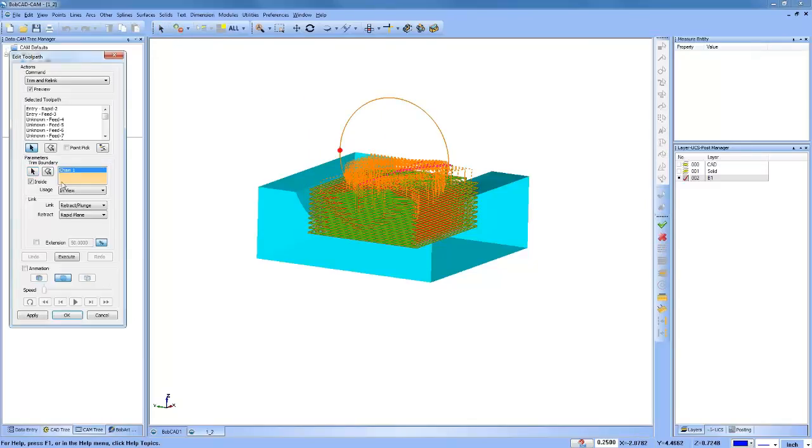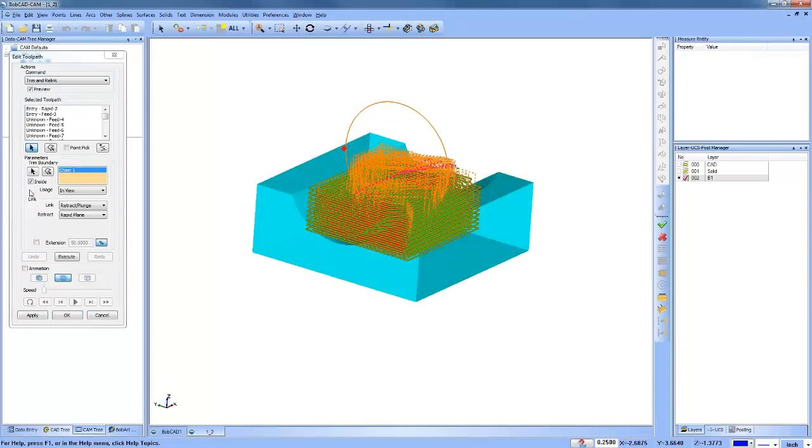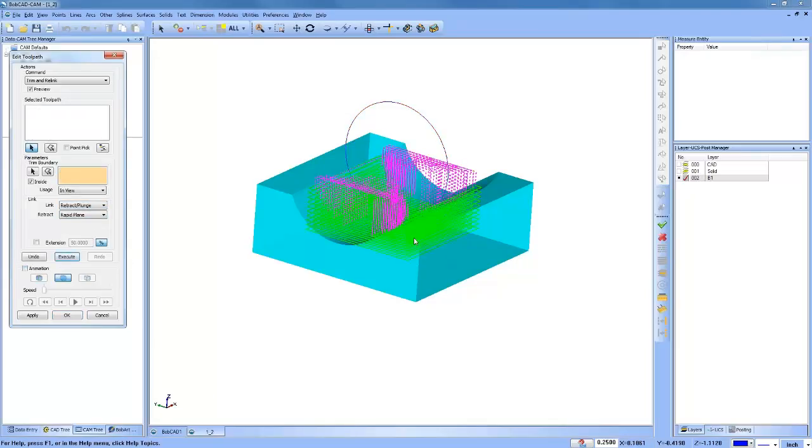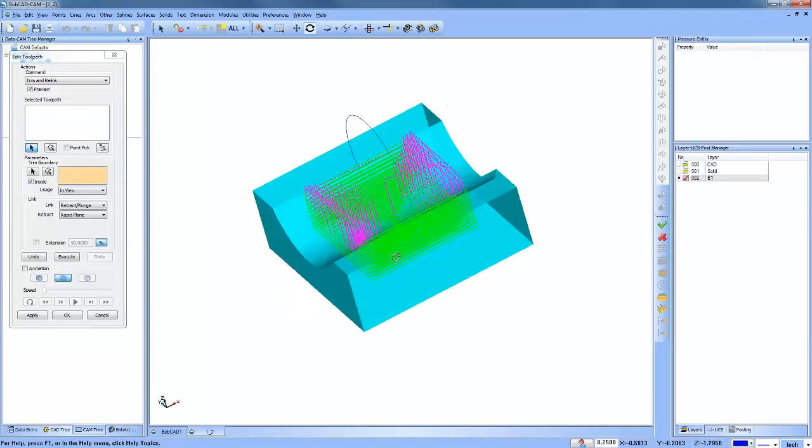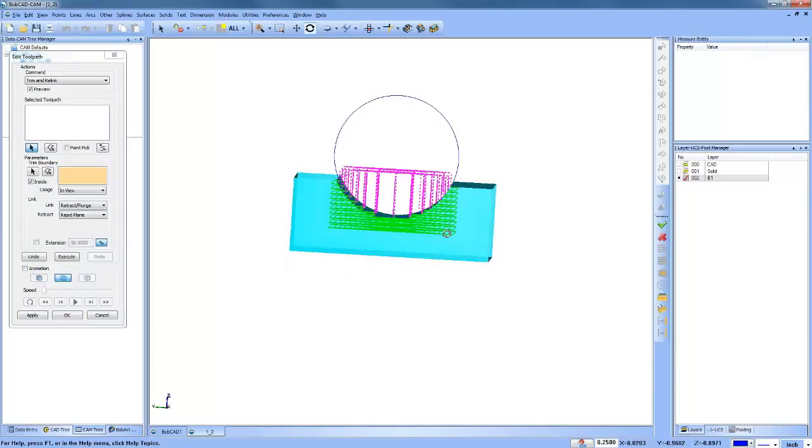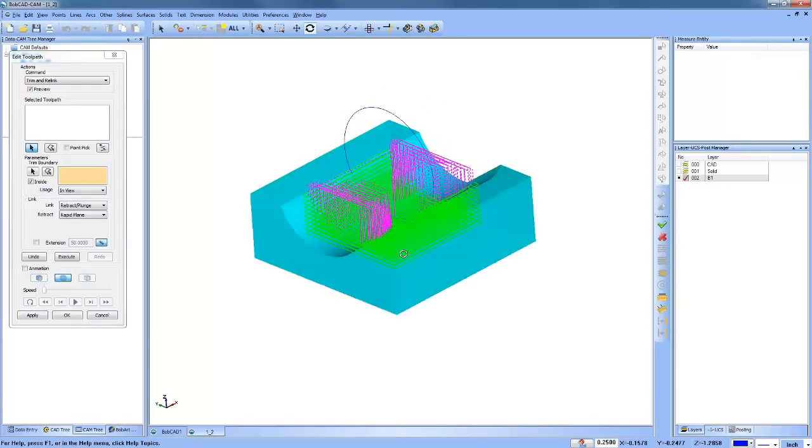Okay. Polygon pick, I'm going to kind of window pick, but a polygon pick in order to get around it. All right. So I have my toolpath. I have my chain boundary. I'm going to do my usage along X. I'm going to do a trim. I guess I could do a retract, so let's do that. We'll do a retract, and you can see what it does is it trims away all that toolpath, and then it runs it back up to clearance.